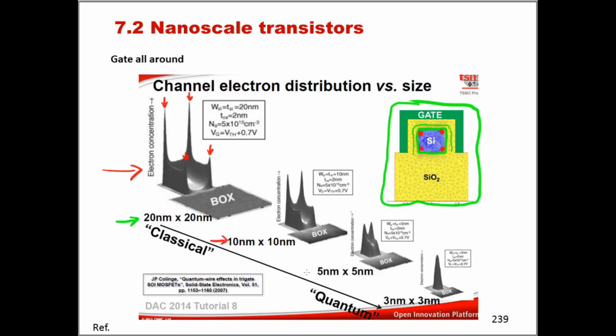As you move to smaller and smaller nanowires, what eventually happens is that the electrons, I will draw this in red, travel just at the center of the nanowire. If you remember, the eigenfunction of the fundamental ground state of our 1D nanowire, if you go back to chapter 3, had exactly this feature. The highest probability of finding an electron was exactly in the middle, and that's what this result here is showing you.